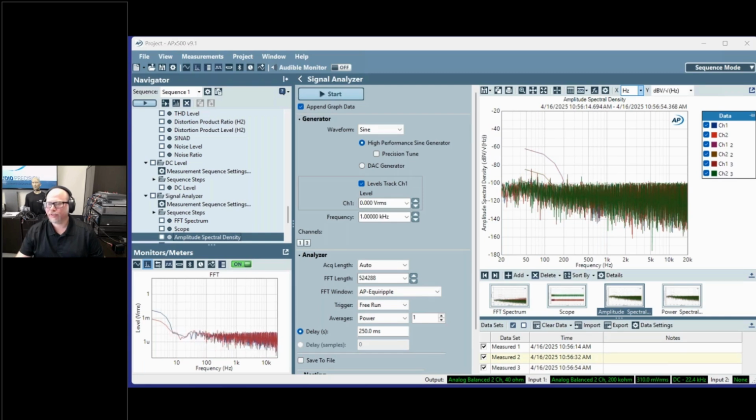Frequency response, there are a few different ways in which it might be measured, but fundamentally what's going on is we sweep a signal across the frequency range of interest while measuring the output level of the device and just plot that. There's nothing too fancy going on.